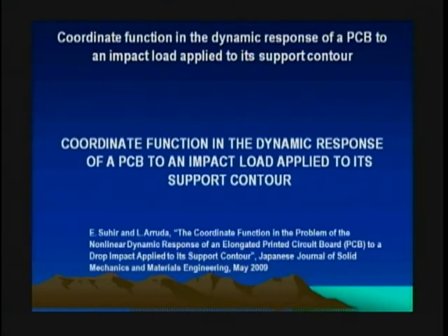the nonlinearity, certainly we saw it, whether it affects only the principal coordinate, or we also should consider that cosine or sine might not fly, or whatever we obtain for not simply supported printed circuit boards. So that's important when we develop particularly test vehicles, and we ask ourselves whether we want to mimic certainly non-simply supported printed circuit boards.